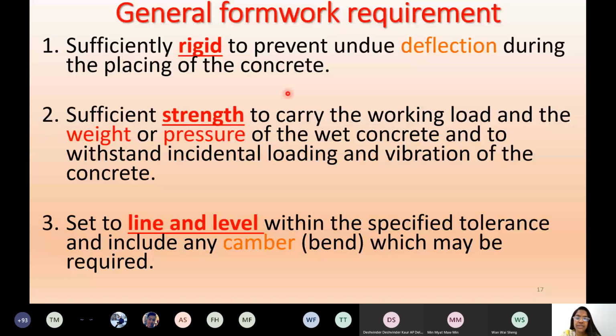Okay, just now I said the concrete will be of different grades. Which grade you are following, M or C or whatever, it has its own strength. To achieve its required strength, I mean the given grade, the curing is important. Concrete, after pouring, is there in the formwork for a certain duration of time to get hardened and eventually attain the strength of concrete. If I say it will bear 20 kilonewton, or 40 kilonewton, it should bear that, only if proper curing is done.